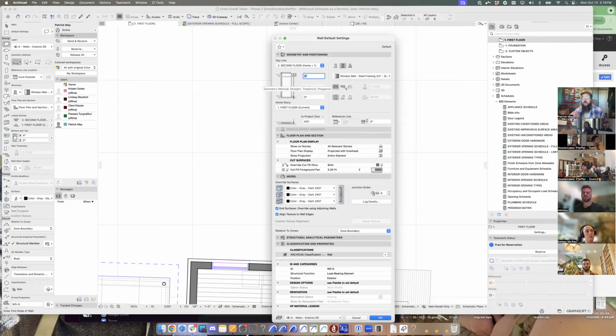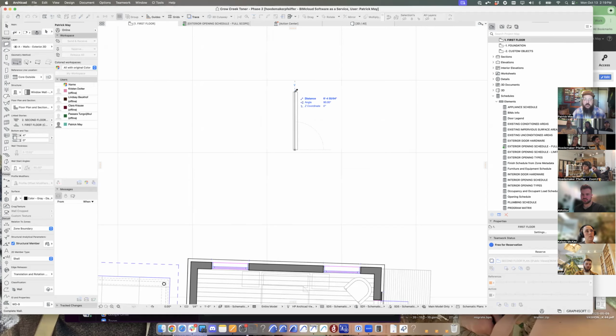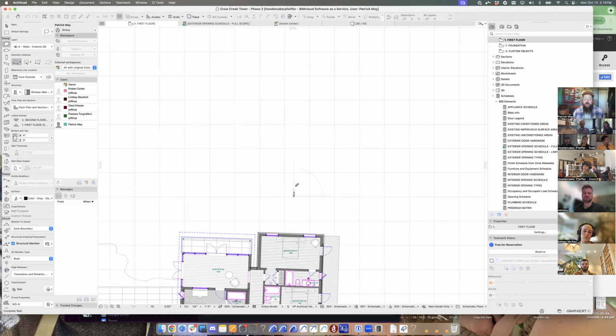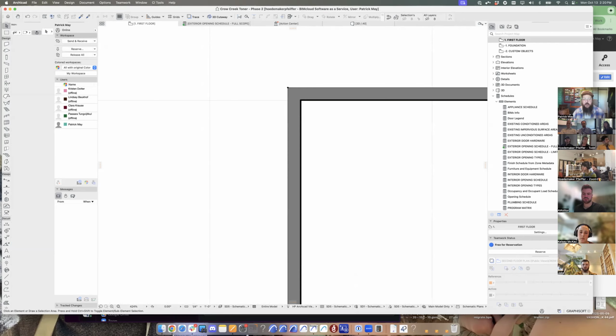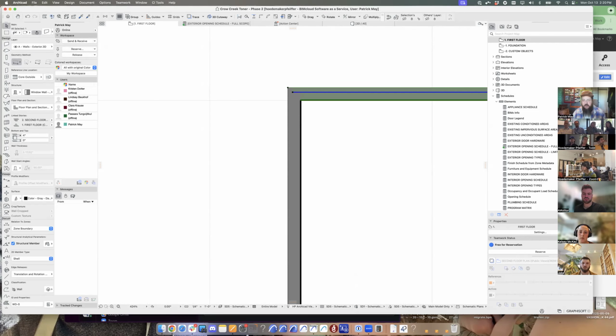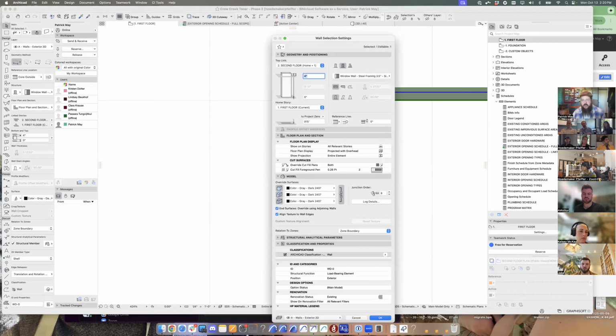As far as what the geometry of that wall is, that can change over time. So as an example, let's say I know that my overall building is going to be 40 by something random like 20, 22, whatever. And I'm just going to draw these walls in here, right? So I have this composite right here. That reference line sits right there. That's the outside of core of that wall.